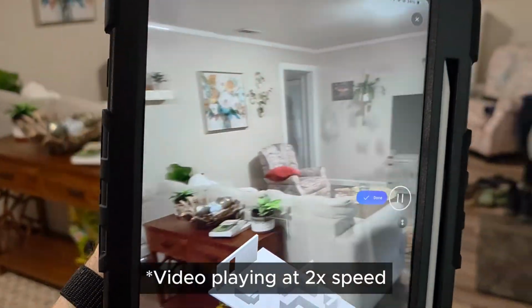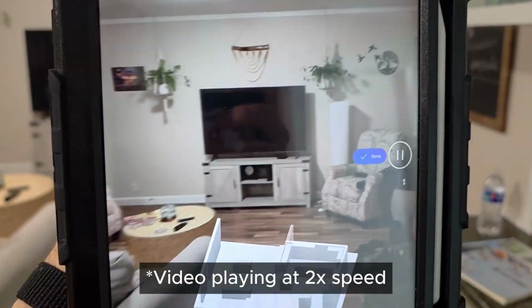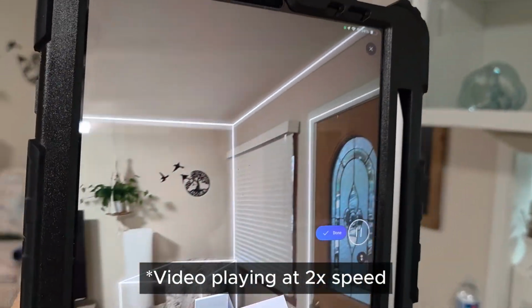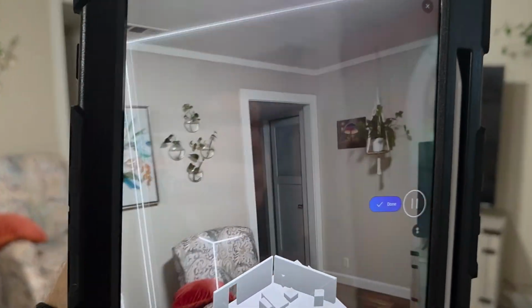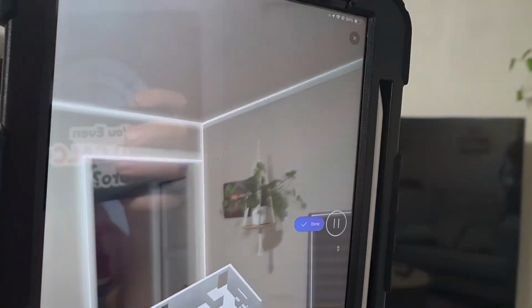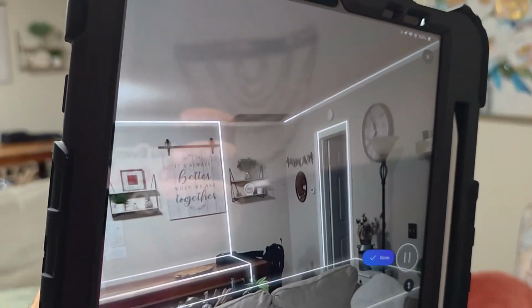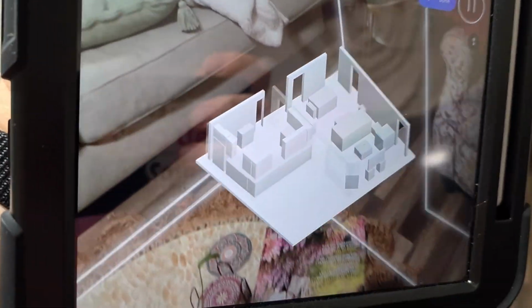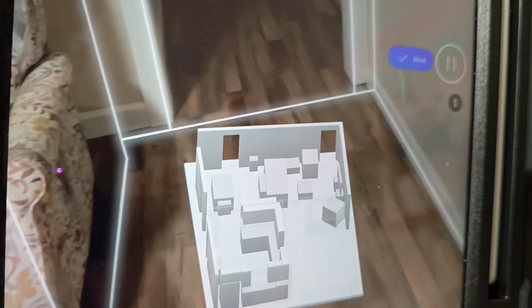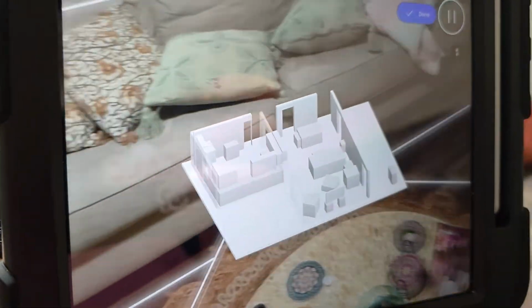Don't rush it. Go nice and slow so that it captures all of the surfaces. And try to go into every room. Even if you can't go into every room, you can easily add and edit rooms in Kwik Model after you import the scan. After you are done scanning, save the scan, and be sure to take photos of the entire outside of the house so that you can double check the windows.